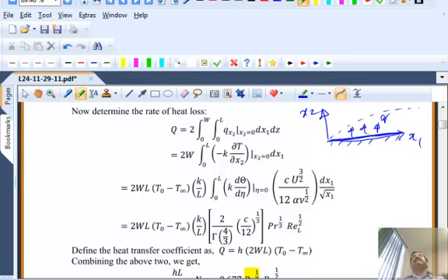You have a condensing medium, steam condensing on one side of this plate. Steam condenses at a constant temperature, right? Or melting, phase change. Whenever you have a phase change, you have constant temperature. So you could have a tube, one side of which is steam condensing, the other side you're heating up some gas. Okay? So that way you can maintain a constant temperature. How do you maintain a constant flux? Electrical heating. Okay, so you just put in electrical resistive heating, and you can maintain a certain amount of heat transfer Q.